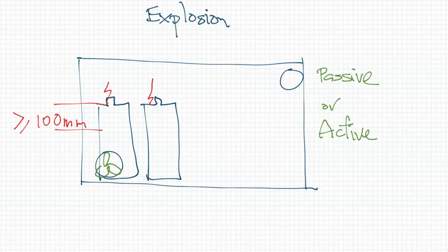Okay. What have we got here? There's a couple more. A flame-proof light's required in the room with lead-acid batteries. So what's called sealed luminaires in the battery standard are required above batteries that have explosive gases emitted. So if it's within what's called the zone, I'll draw this again. So I bring my drawing tablet back up.